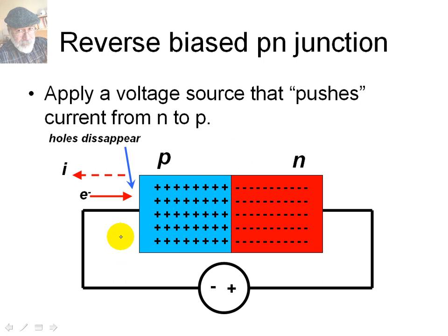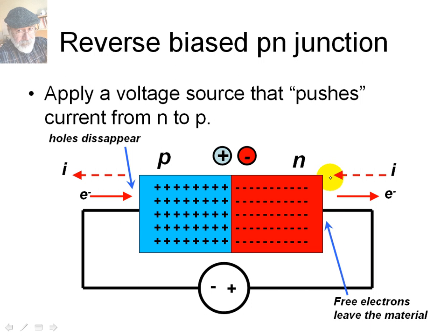At the same time that we have holes disappearing on the left-hand side of the p-n junction, that attempt of the external source to feed new current into the N material will be materialized by an extraction of electrons, which will reduce the density of electrons on this part of the p-n junction. That difference of density in holes and electrons will get the holes and electrons move away from the junction to even out the density of carriers in the p-n material bands.